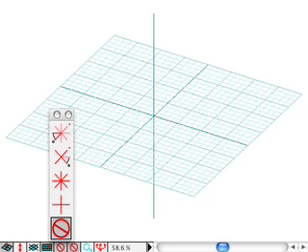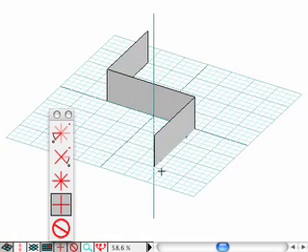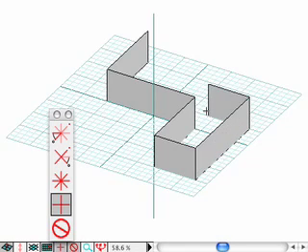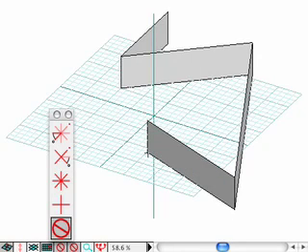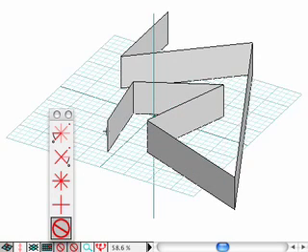Next, we discuss directional snapping, which constrains the input points to a vertical direction, horizontal direction, or diagonal direction. Select OrthoSnap and draw a shape. Observe that the input points are constrained to the horizontal and vertical directions. Select No Direction Snap and draw a shape, which is the default. Observe that the input points can be clicked in any direction.